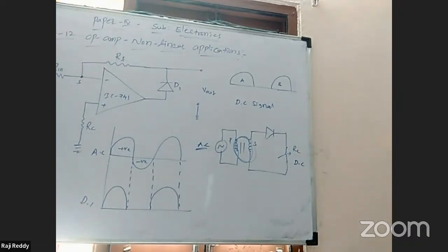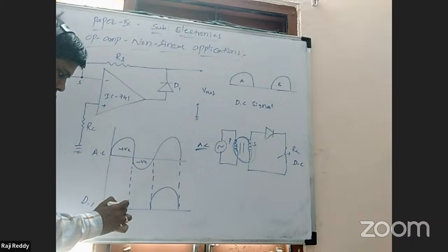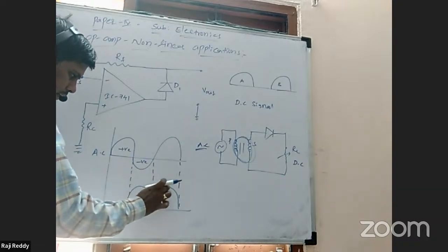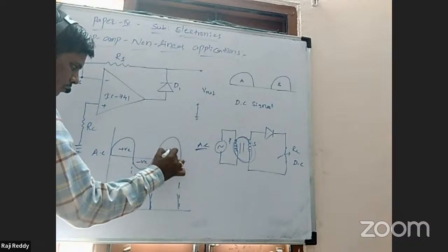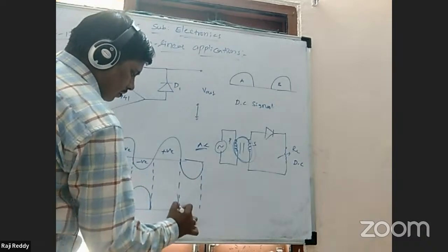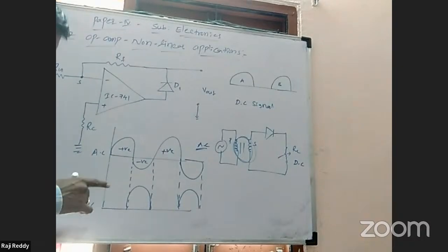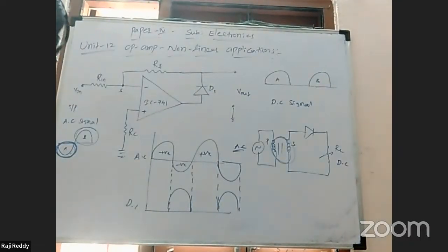Here first we are giving negative. So instead of the positive pulse, only the negative is converted AC to DC. The positive it won't convert, so positive remains as it is. The next negative pulse it can convert, and the next negative pulse it can convert. So the output is DC only. So finally you can say the output is a discontinuous DC pulsating output. Is it clear? Right. It is a discontinuous DC pulsating output.